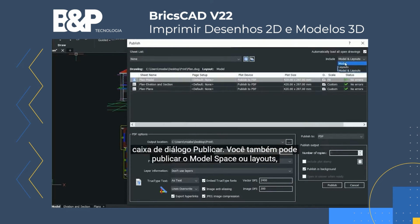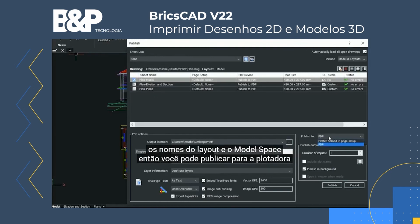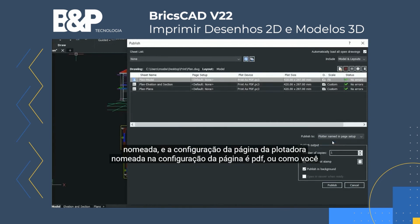Now we have various options in the publish dialog box. You can either publish the model space or layouts or the model and the layouts. You can see everything here, the layout names and the model space. Then you can publish to the plotter named in the page setup.